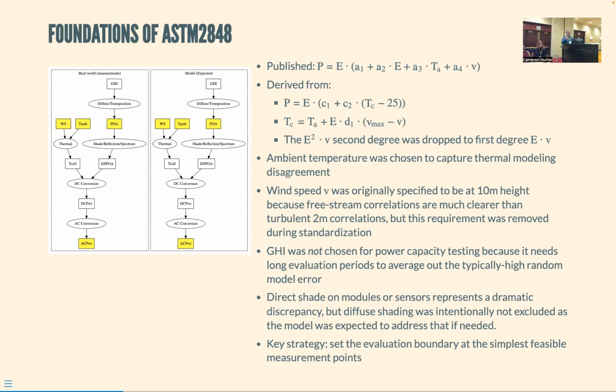But a basic fluids class will always talk about the free stream flow, which in our case we would assume is a 10-meter high anemometer. If you put the anemometer at the elevation of the modules, you'll experience a lot more turbulence, and it'll be harder to see what's actually going on, because you're in such a localized position that you can't see the average behavior easily.